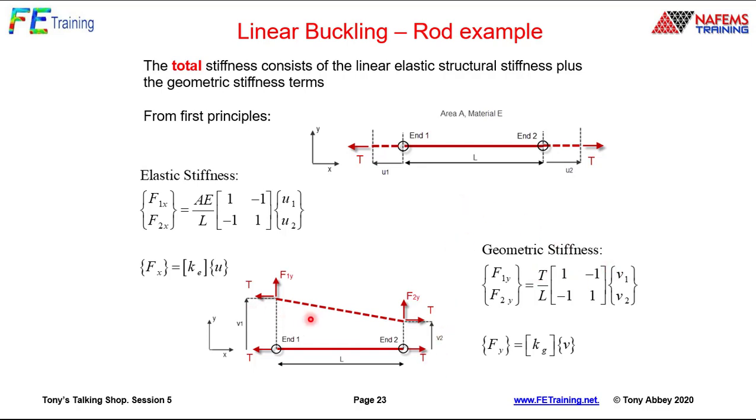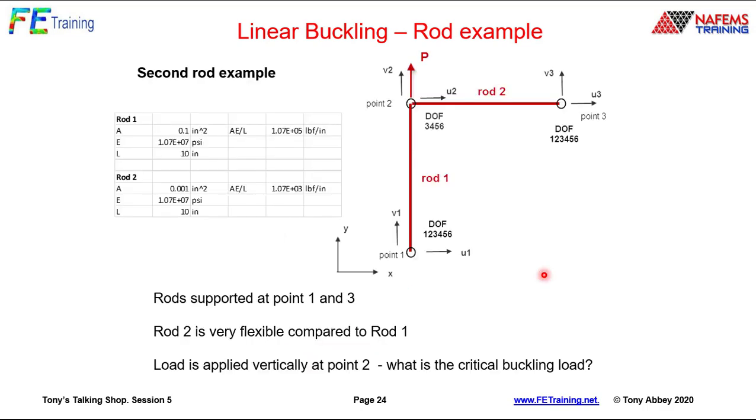Now we do a big cheat, and we assume that geometrically T is actually lined up, so we ignore the little angle which is in here. Again, small deflection theories, lots of assumptions coming in here. I can do a moment balance at both ends and come up with that little matrix in there. So it's a very simplified nonlinear stiffness matrix, but it's enough to get that stress stiffening term in there. That T is the critical term in my geometric stiffness matrix.